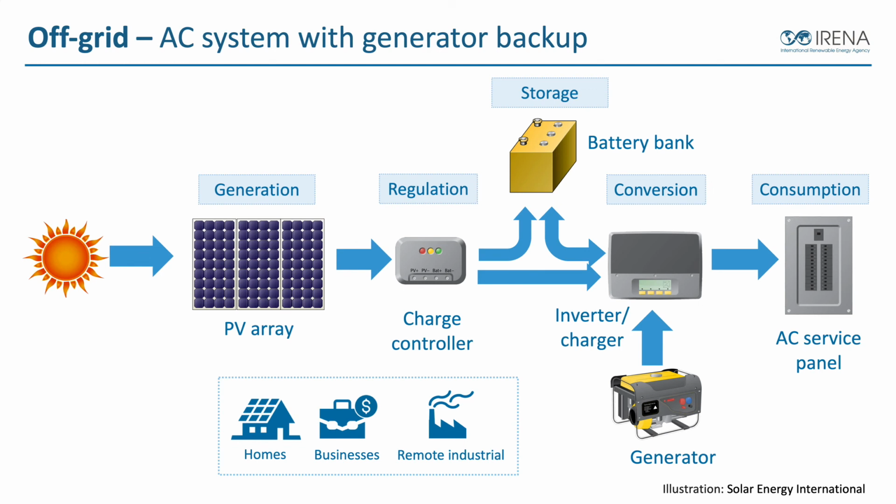We just need to know that if we intend to work with a generator in a system like this, we want to select the right generator and the right inverter, not only sized to match my needs, but it also needs to have these additional features of generator control, which allows a more seamless integration and a more autonomous system that doesn't have to have the generator started or monitored by a person, but we can program it to operate automatically. And that gives us a much more reliable and independent power system that someone doesn't have to pay very close attention to all the time to make sure that we have power 100%.